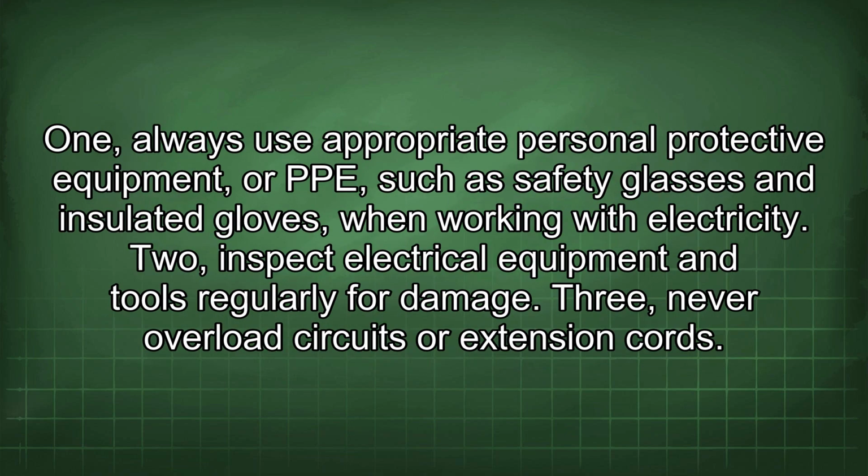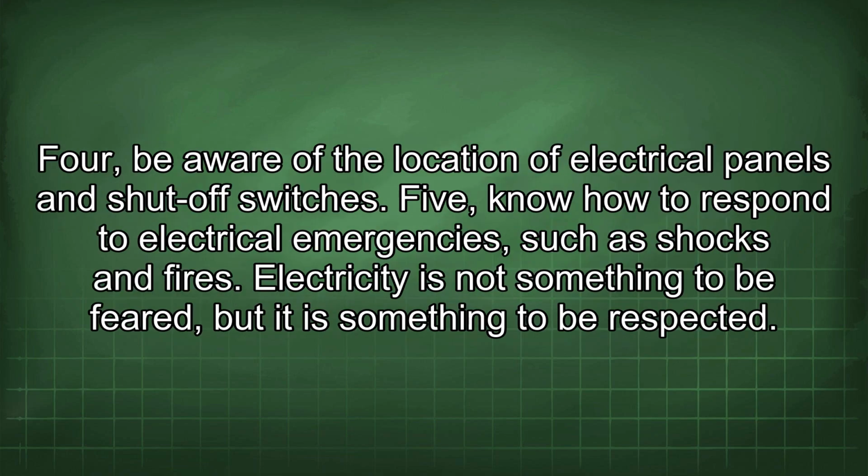1. Always use appropriate personal protective equipment, or PPE, such as safety glasses and insulated gloves, when working with electricity. 2. Inspect electrical equipment and tools regularly for damage. 3. Never overload circuits or extension cords. 4. Be aware of the location of electrical panels and shut-off switches. 5. Know how to respond to electrical emergencies, such as shocks and fires.